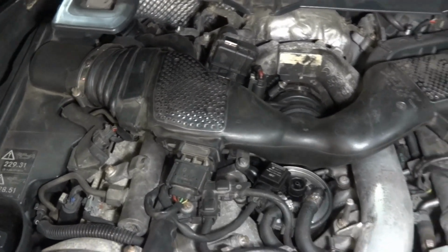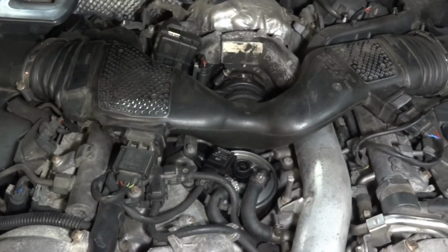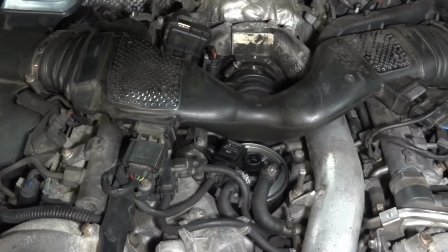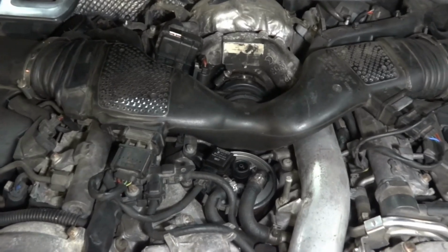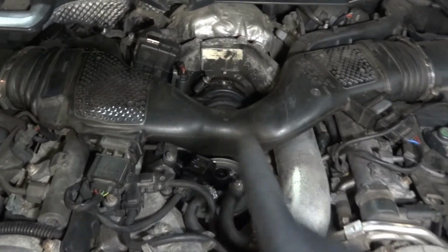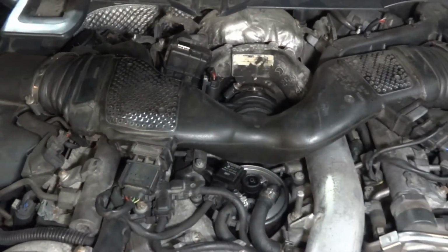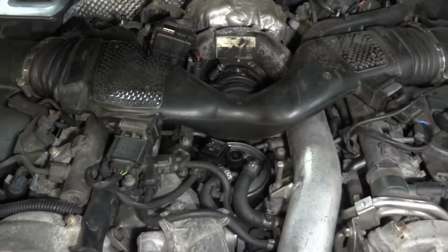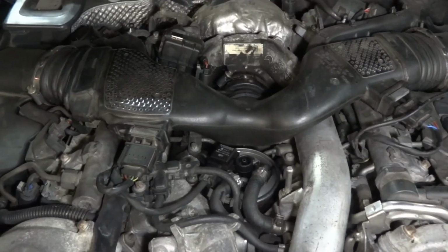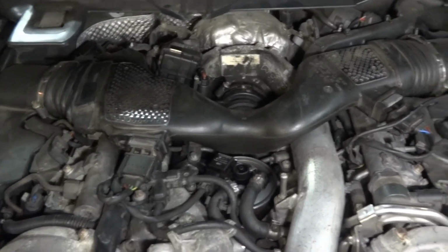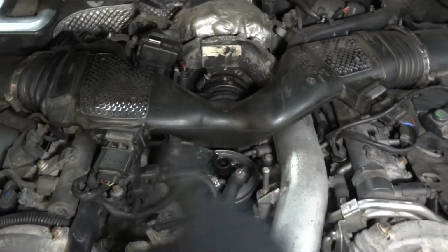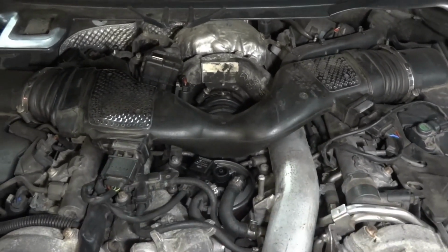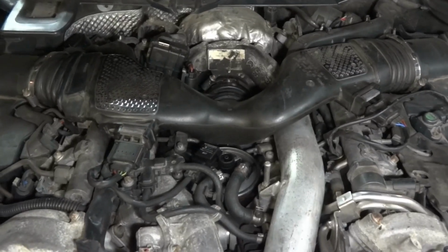I have a used actuator somewhere here. We're going to connect the used actuator and do the same test to see if the actuator that I have will make the same clicking sound like this one is. If it doesn't make that clicking sound, that will once again confirm to us that this actuator is indeed bad. Okay, so I'm gonna get this tube out off camera, and then I'll bring you guys back up.